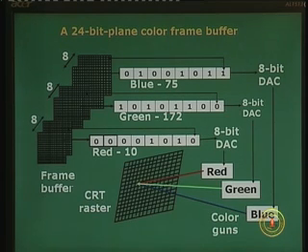That is also displayed. So that means we are going to display a particular point with a color intensity where the red component will be 10 out of 256, you can take a fraction of that, green is 172 also out of 256, and blue is 75 out of 256. Basically the programmer doesn't need to load values like this. It typically loads in a normalized range from 0 to 1, and the values are put onto the bit plane, and then automatically loaded onto the register, which again drives an 8-bit DAC. Now we need 3 8-bit DACs, 3 color guns, 3 8-bit registers, and a 24-bit plane. So that's a huge demand on the bandwidth and memory requirement, and these color guns will of course ignite the phosphor dot triangle on the screen to emit this color.